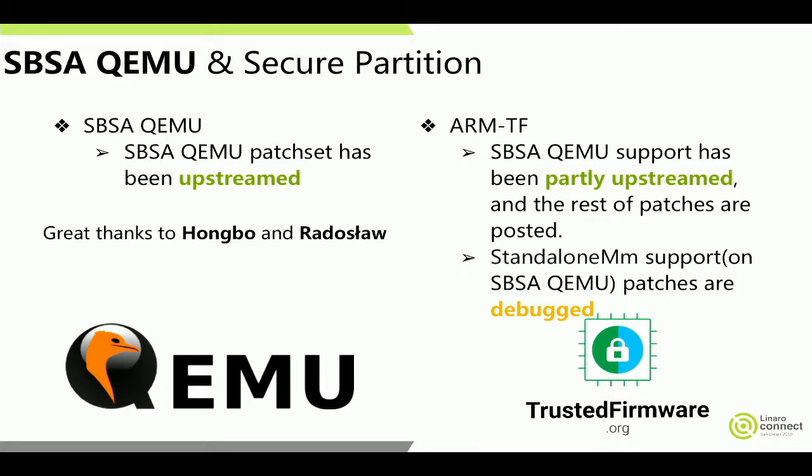The standalone MM support patch for SBSA QEMU, I'm still debugging, because if you want to include a standalone MM in your firmware, in your FIP, it will be very large, 2 megabytes.